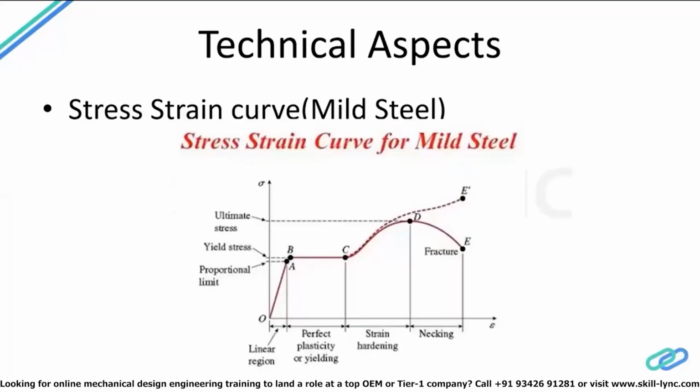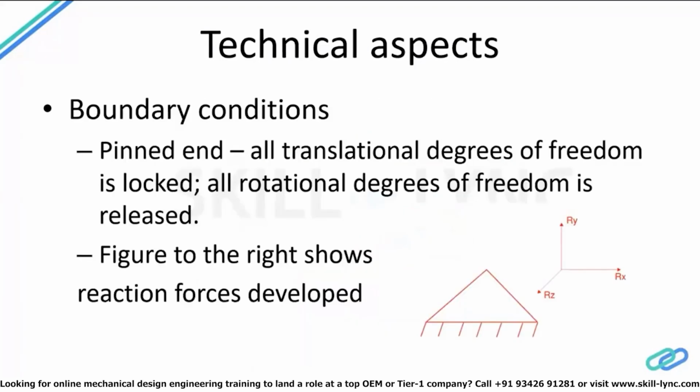To the material, the other thing which governs the behavior of a member is the boundary conditions, right? So for example, any structure will have different supports, be it a pinned support, a roller support, a fixed end support, or it could be springs as well. We'll look at some of those and the different aspects of them, and the different real life examples of these boundary conditions.